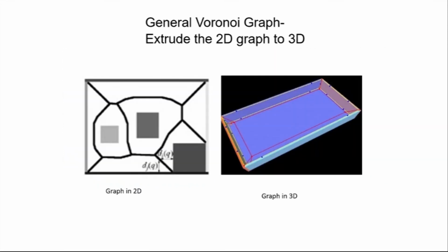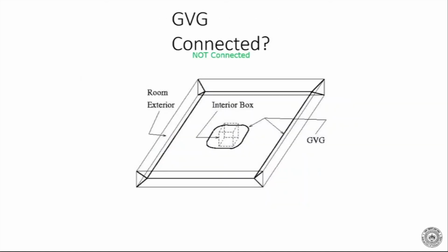Now, here we can also have it in 3D. What I just explained was in 2D. We can do exactly this in 3D also. So in the 3D case, we deform it in this direction. This is the side wall, and this is the obstacle, right? When we are deforming it, this is my retract now. Now in case of 3D, how will it come? You can see that this side wall is there. This is the floor. So there are 3 lines now, one line here, one line here, and one line here, the 3 edges. So what will the deformation retract look like? It will look something like this. This line is the equidistant line, and the center line is here.